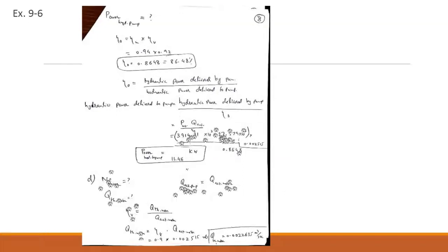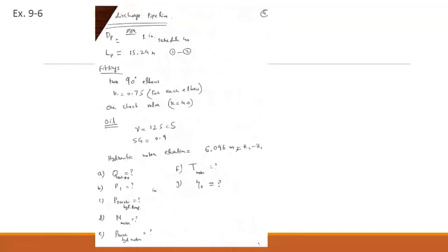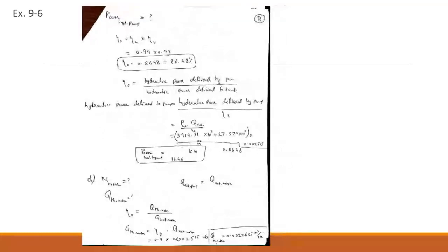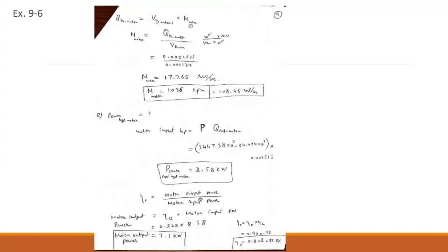If you want to find this one, we have the volumetric efficiency of the motor given. We have the actual motor flow rate, which is again coming from the discharge volume flow rate from the hydraulic pump. You see here actual motor, it is the value which was calculated over here. Here you go, this value is put here, and you get the theoretical volume flow rate. Why do we need it? Because when we have this, we can use the volumetric displacement of the motor and find the angular velocity. Since we have the theoretical volume flow rate, we just divide by this, and then we get it.